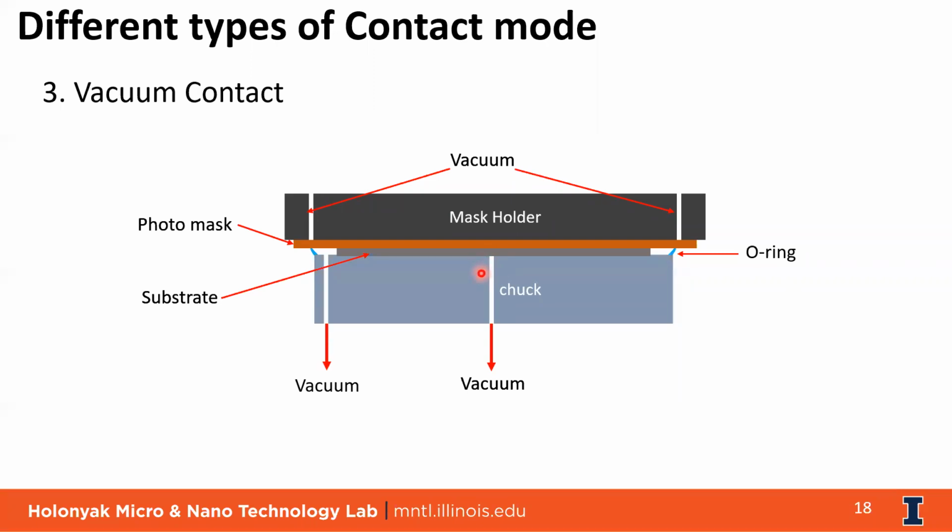But vacuum plus hard contact really affect your photo mask only at certain conditions. So where you have any particle left on your sample during spin coating, that particle gets crushed between the substrate and the wafer, it can seriously damage. But if your coating is very uniform, you do not have any particles. So if you are doing it in a controlled way, it doesn't affect that much.